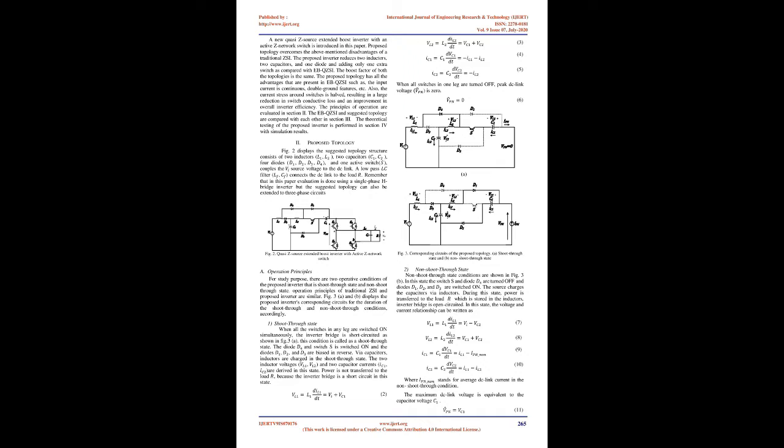The boost factor of Enhanced-Boost Z-Source Inverter with switched Z impedance, EB-ZSI, in [9] is very high and its expression is given in (1), where B stands for boost factor and the shoot-through duty cycle is represented by D. The proposed topology also suffers from certain drawbacks such as different ground points between DC supply and inverter bridge and the input current is discontinuous. To overcome these drawbacks, a new topology, Enhanced-Boost Quasi-Z-Source Inverter, EB-QZSI, is proposed in [10]. The proposed inverter provides continuous input current by using 2 switched impedance networks. The proposed inverter escapes the above-mentioned disadvantages in [9] and maintains a high boost factor.